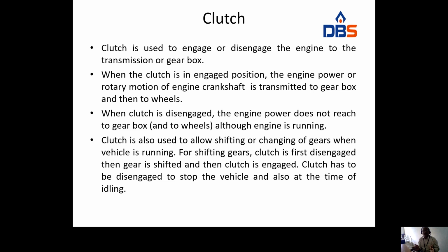To transmit the power, they designed a component called clutch. Clutch is a component which transmits the power from the engine to the gearbox. Clutch is used to engage or disengage the engine through the transmission or gearbox. When it is engaged, it transmits the power. When it is disengaged, it stops the transmission of power. Already we have discussed all these things. In this class, today we will discuss how the multiplate clutch works.